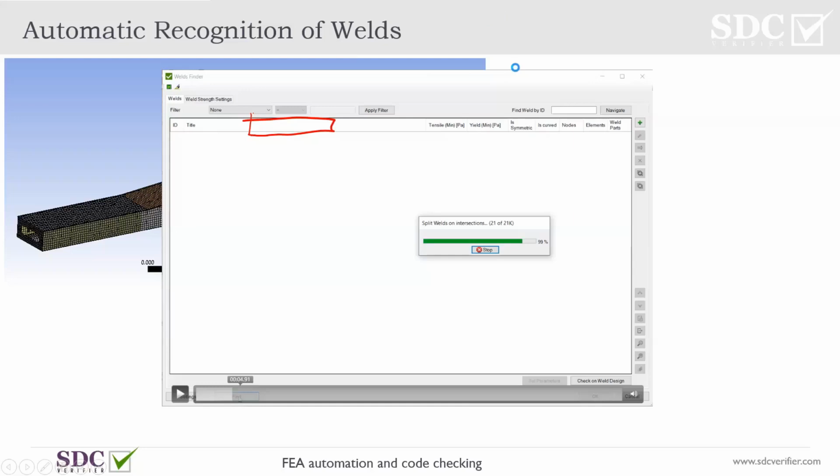We also need to know the pattern of usage of your crane. So for example, if you have a basic input, what is the typical ship size I have, so that I could identify what the trolley positions normally used are? That's good enough, because in this case I can come up with the typical pattern of the trolley movements and then avoid this conservativity with the extreme positions. So in short, if we have typical input data according to specs and an idea of the trolley usage, that's enough to allow that.